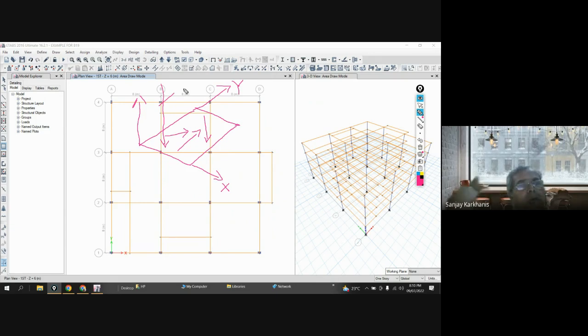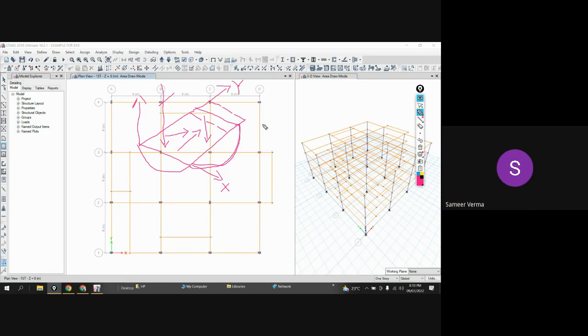That's why it is called out of plane. Now this out of plane load will create bending, depending on slab thickness, slab aspect ratio and supports. It will create either one-way bending or two-way bending. But in-plane loads will create either extension or contraction. Right?